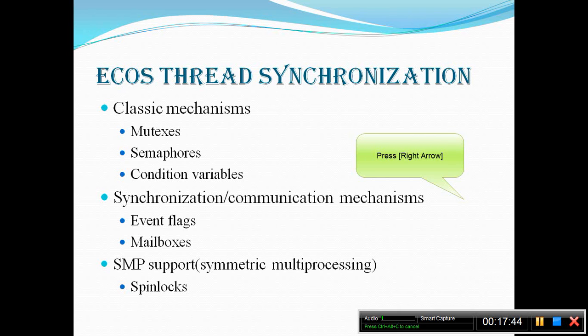The next command, cyg_semaphore_wait, checks the value of the semaphore count. If the count is 0, then the thread calling this function will wait for the semaphore. If the count is non-zero, then the count is decremented and the thread continues. Counting semaphores are suited to enable threads to wait until an event has occurred. The event may be generated by a producer thread or by a DSR in response to a hardware interrupt.